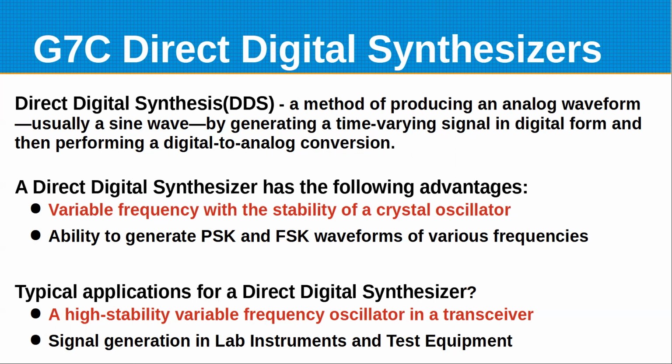So a direct digital synthesizer has the stability of a crystal oscillator, but it's still a variable frequency over a wide range. You don't have to buy hundreds of crystals. And you don't have to buy different crystals, right? So that's becoming much more common in modern radios, to do a direct digital synthesis of your VFO signal or local oscillator signal.